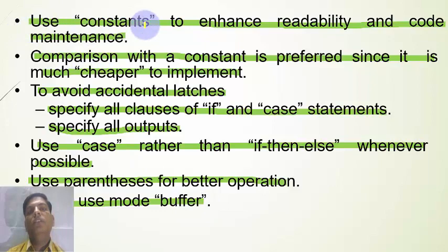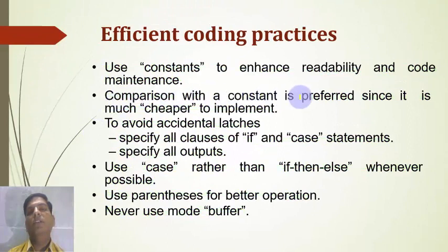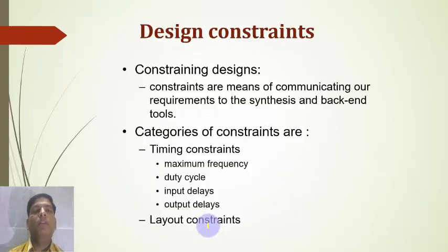Again, use constants to enhance the readability and code maintenance. Comparison with a constant is preferred since it is much cheaper to implement. To avoid accidental latches, specify all clauses of if and case statements. Specify all outputs. Use case rather than if-then-else whenever it is possible. Use parentheses for better operation. Never use mode buffer.